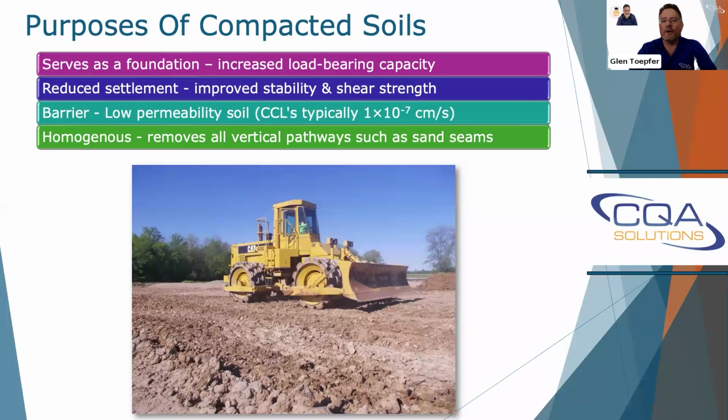What is the purpose of compacted clay soils or compacted soils? I keep calling them clay, but they don't have to be clay. I'm just used to dealing with primarily clay liners, but typically they're going to serve as a foundation, and that provides increased load-bearing capacity, such as structures for roadways, reduced settlement, which improves stability and shear strength.